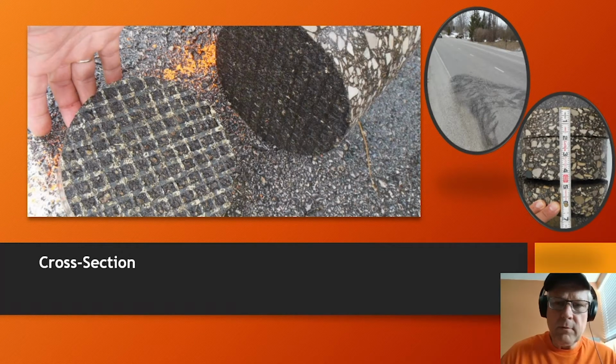Fabrics, grids, whatever product is used on road pavements, they need to be deep enough. They need to be installed properly. We don't want to put some type of grid system less than 2.5 inches deep. Many times I'm involved in projects that have very shallow depths, and at the high stress areas they begin to break and slip. Quite often the asphalt's blamed for this, but it's most often the fact that this is a bit of a bond breaker, and then when they're not installed properly, they'll cause challenges. So again, products can be used successfully, both geotextiles and grids, at the proper depth with the proper installation, and certainly under the proper traffic loading.